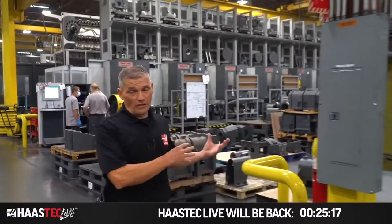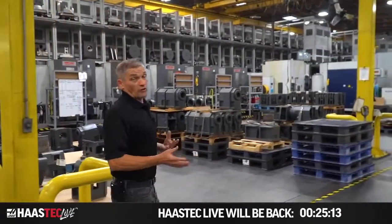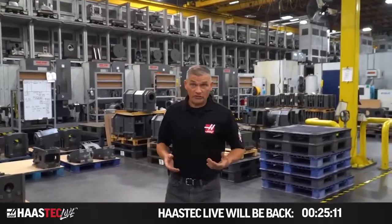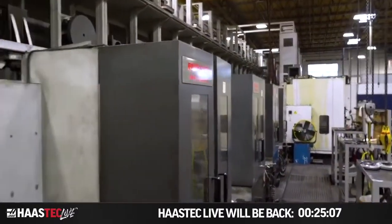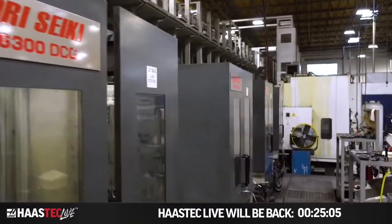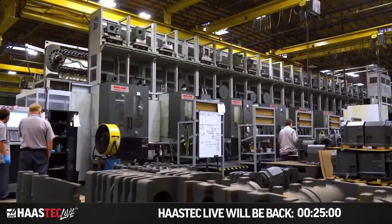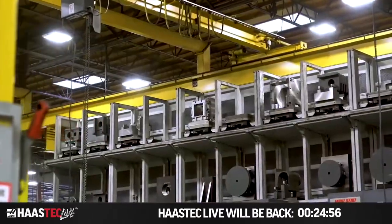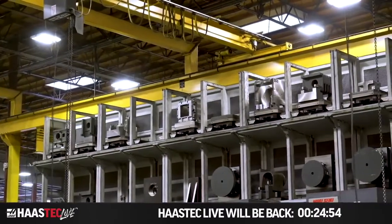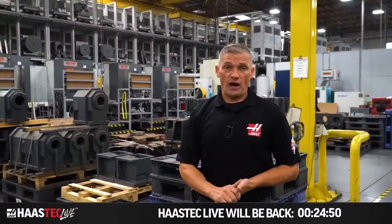All right, this is gonna be the last FMS that we'll look at today. This here is one of the largest FMS systems in the entire world based on the number of load stations and the linear number of pallets involved. Here we've got a really large mix of parts. You can see all the castings up there on the pallet wall. Lathe spindle heads, lathe gearbox housings, tailstock housings, just a really wide variety of parts, all made basically just in time for the production line.